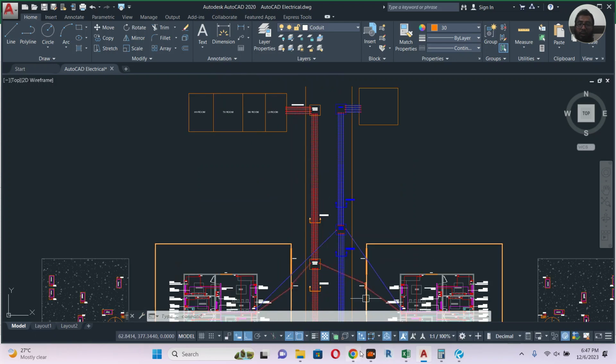And you can go for the thumb rule, just 1.54, just keep it in your mind. Okay, I have 20 kilowatts power. What is the ampere? Just multiply with 1.54. That's why I use 1 kilowatt. So if you don't remember 1.54, just keep it 1.6, no problem. But as per the power factor, it can be changed. So generally some areas use 0.8, so 1.745 something will come.